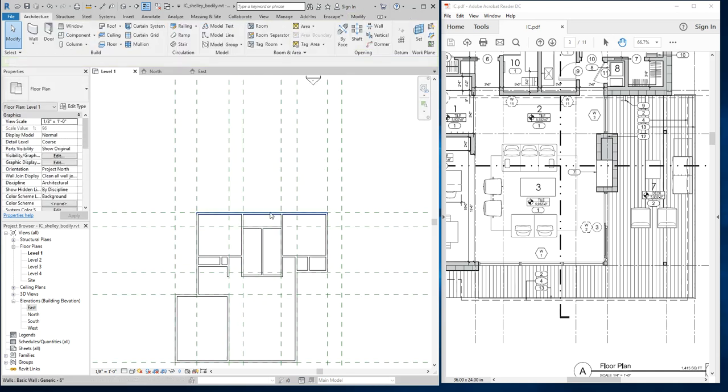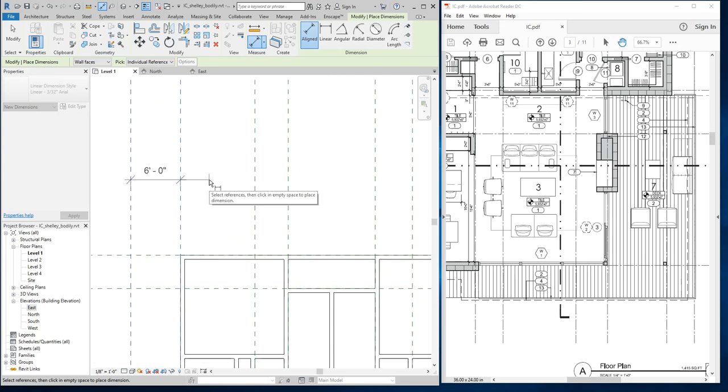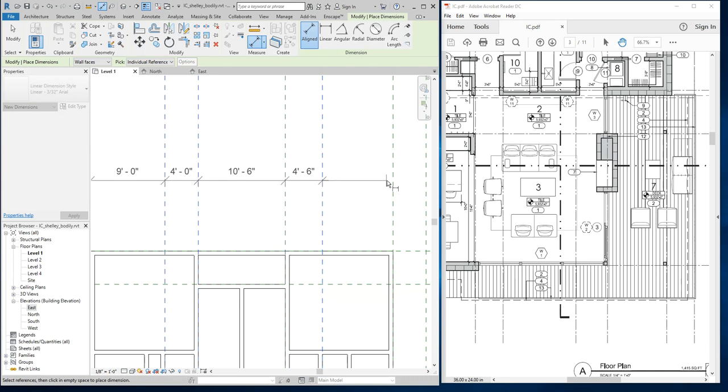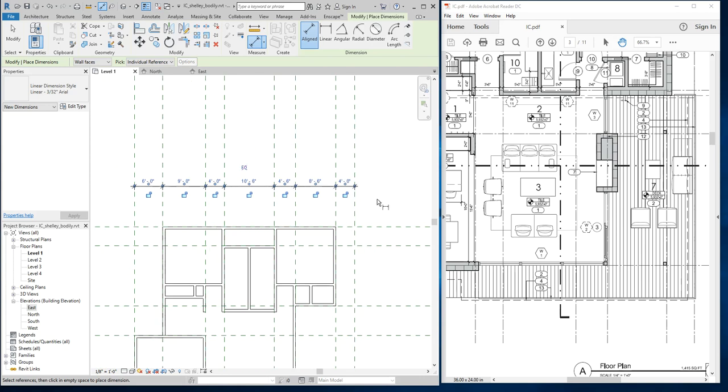If you wanted to put some dimensions on your grid, you could use that same tool we'd been using to leave dimensions there, right? So I could come in here and type DI for dimension, and I could just click and click. I'm moving forward a little bit, but I could just continue on, right? I don't end the dimension until I click in space. So I could just continue to add dimensions if I wanted to, just to make sure, click in space, right, that those things were looking the way they should.